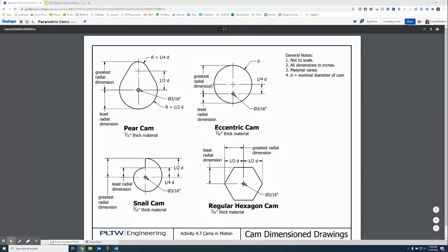For example, we have variables. Instead of an actual number, the diameter is defined in terms of a variable. And all of the other dimensions of this eccentric cam, with the exception of our hole, use this variable. The reason we would do this is it makes changing the size of certain features and overall shape pretty easy once it's done correctly.